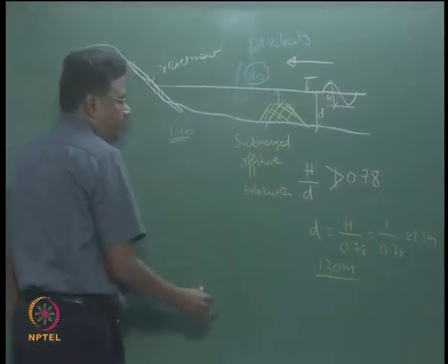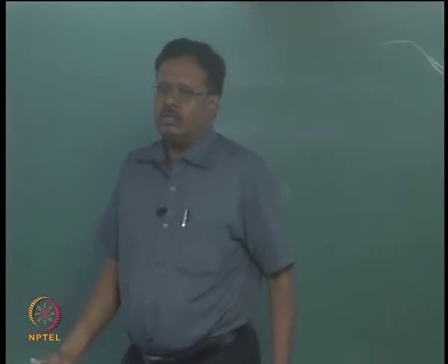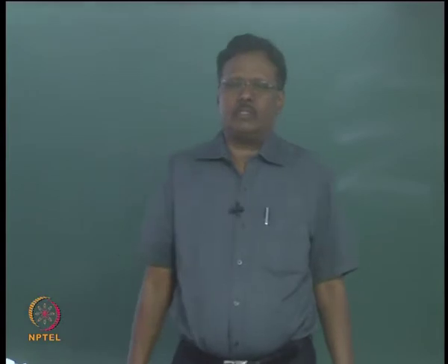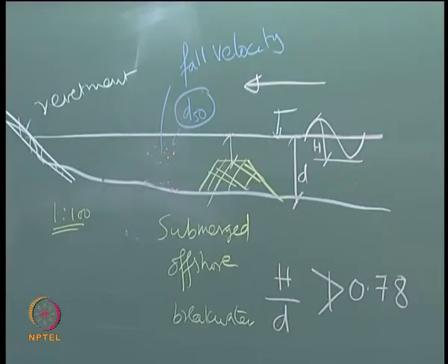Clear? No, due to wave and current you have a velocity, if that velocity is more, the sediments will be suspended or it will pick up some sediment from the shore causing erosion. If the wave and current velocity is less than the fall velocity, then the sediments will settle down.